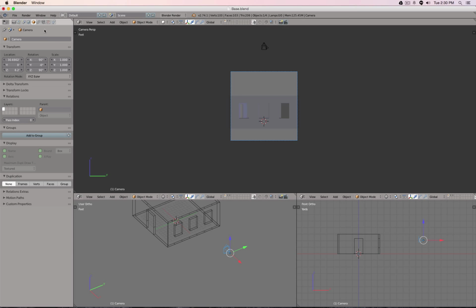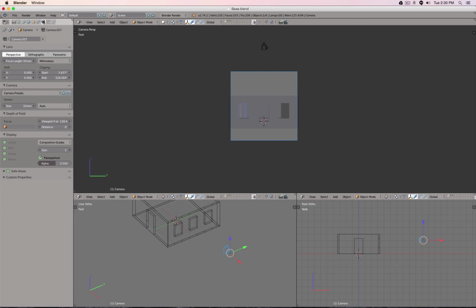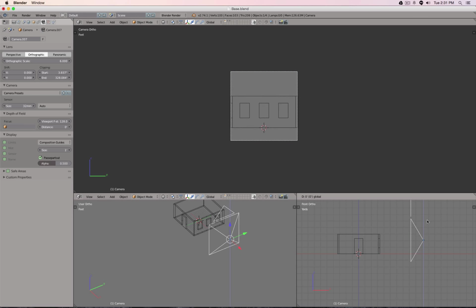This is perspective. Maybe we would like this to be an isometric, orthographic elevation view. So we go to the camera properties while having this camera selected. And here you see we can switch it to orthographic. Click. And let's go into wireframe. There you see perspective, 2D, perspective, 2D. If I move my camera up, it goes up and down. If I move my camera forward, backwards, doesn't really matter. Because now we have a scale function with which we can decide the scale. Pretty easy.